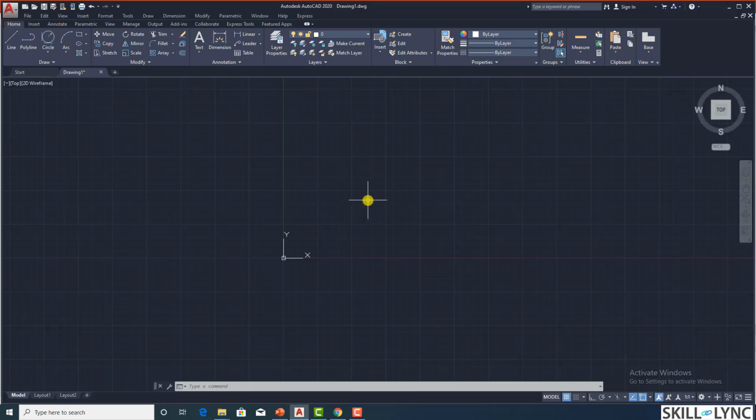So next, moving on to the next part, that is the 2-point circle. So again, invoke the circle command by C, and then for invoking the 2-point, let us enter 2P. Which letters should you use? It's highlighted by the dark blue color listed here. So by typing that, you are invoking the shortcut to that command.